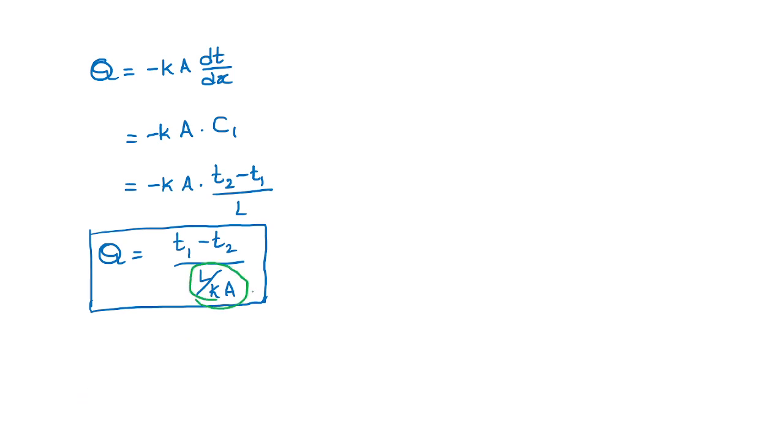This L by kA is nothing but the thermal resistance due to conduction. So this equation is similar to Fourier's law of heat conduction, and the assumptions made here and in Fourier's law of heat conduction are the same.